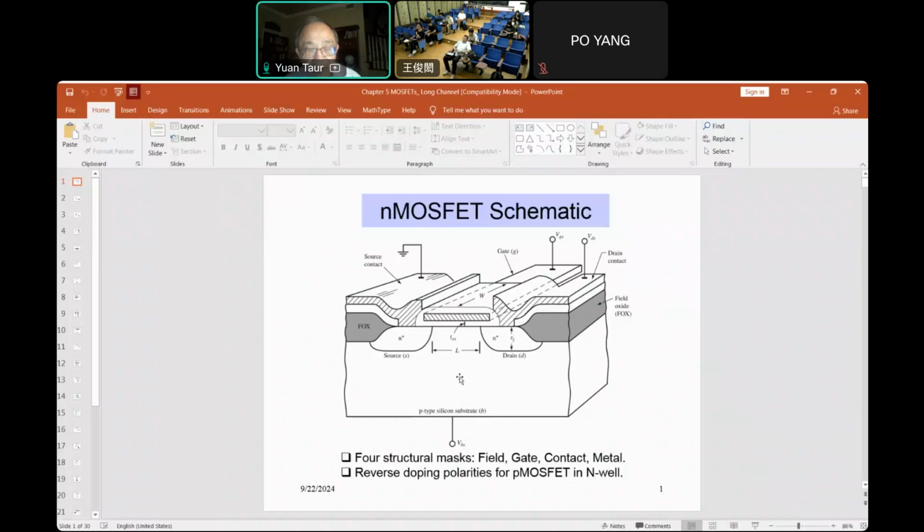It is also called unipolar because for NMOS you only worry about electrons. You don't have to worry about holes because the PN junction is mainly for isolation and doesn't play any role. In chapter 7, when we talk about SOI, you can see that you don't really need a P-type substrate. It can be undoped and still work, as long as there's no conduction current before the gate is turned on.